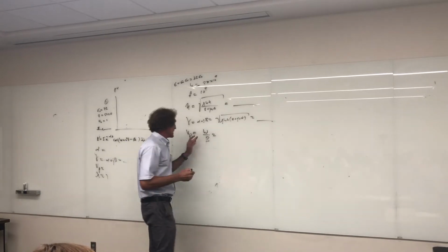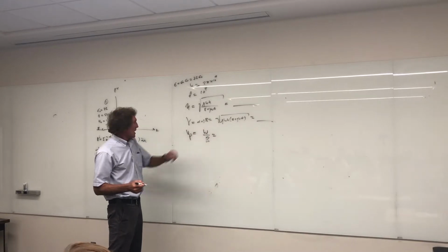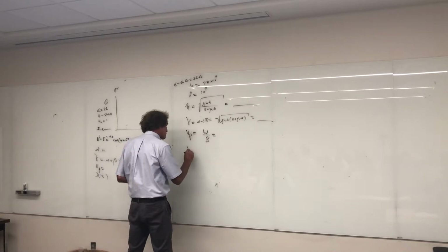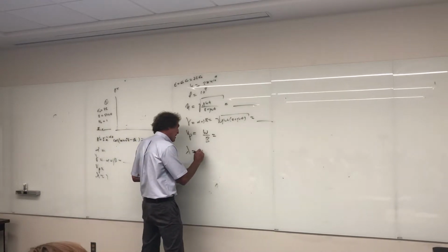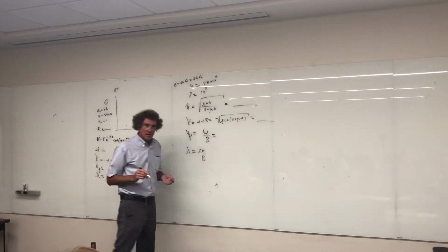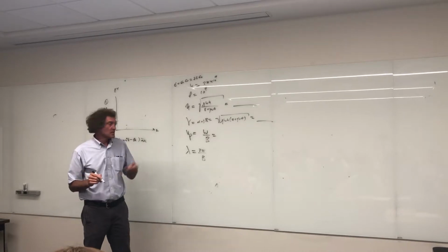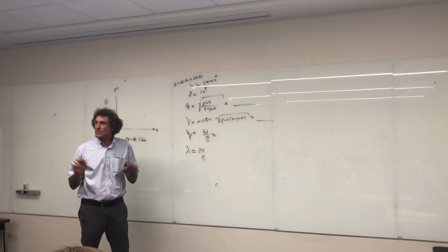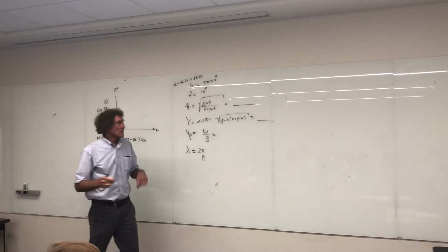All right, that's this, right? We get beta from up here, don't we, guys? And they want wavelength. Now, what's wavelength? Well, technically it's 2 pi over beta. That's the best single definition, isn't it, class? That's fundamental. Some people say it's phase velocity over frequency. That's fine, too. But this is the fundamental one. Got it, guys? So let's go about getting them.